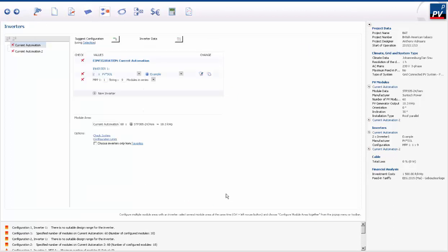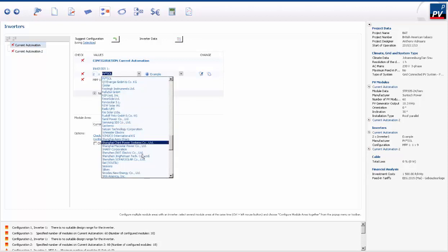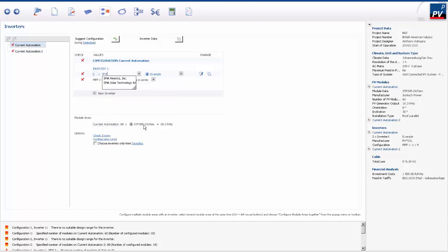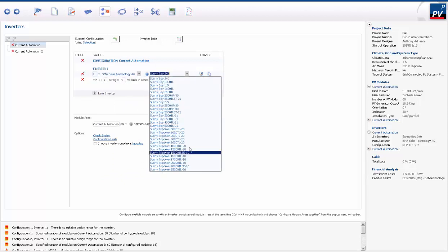And you go to your inverter. So you must do it roof for roof. First we select the inverter. Let's say we're doing SMA. And you pick what is 60 modules? 60 times 300 is 6 times 3 is 18 kilowatt. Alright? Set price?